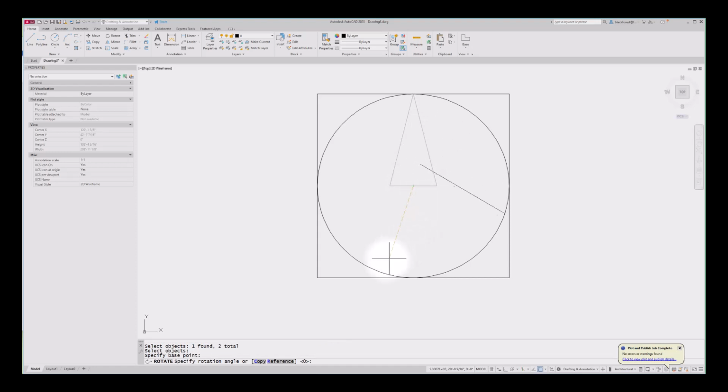And you'll see now that it'll rotate wherever I want it to go. So the longer you have this little dash line, the more control you'll have over it. If it's right here, it's kind of hard to control, so you can really extend that line out and have a lot of control over it. Now with your ortho on, you have a lot of flexibility to click it here, here, or here. So let's go ahead and do that once. We're going to go ahead and select that corner right there. So now we've moved that to the side.